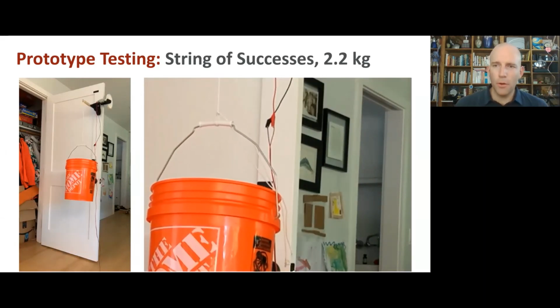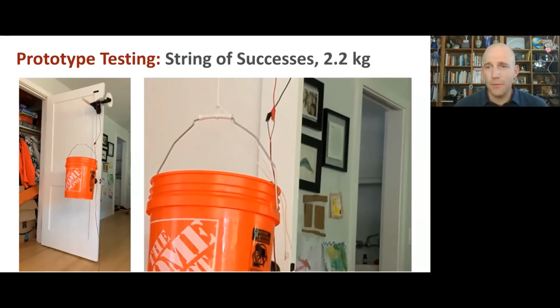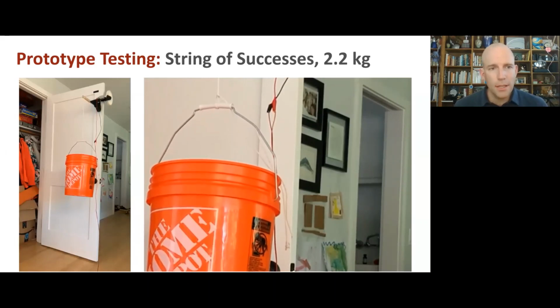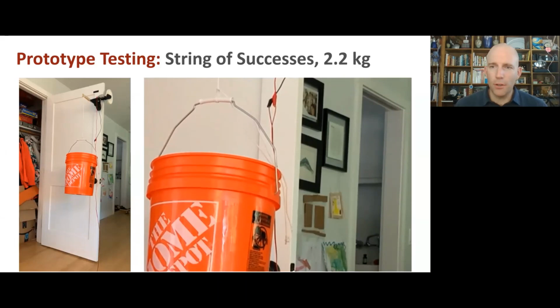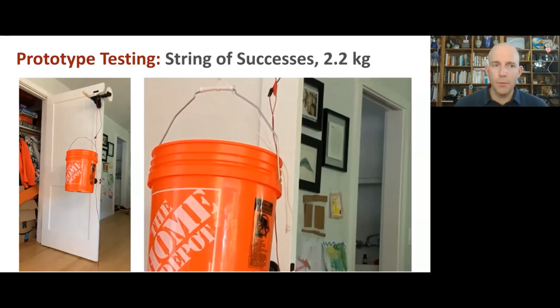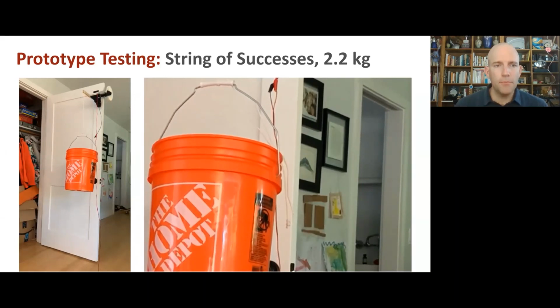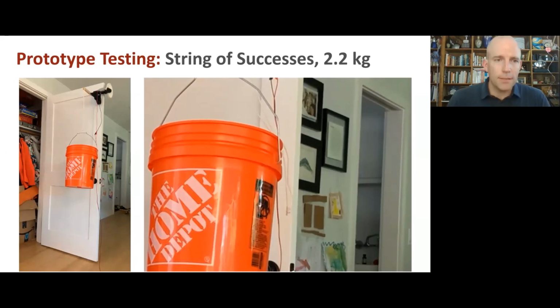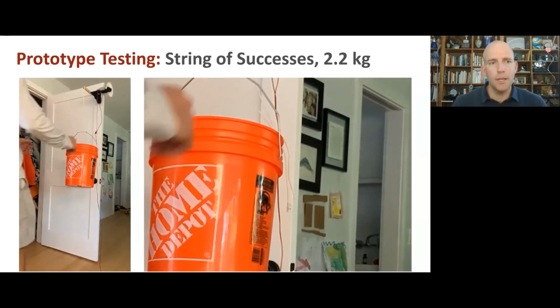And so I've jumped forward a little bit here because it's kind of a boring video. It just very slowly climbs up. It took about 2 minutes. We're not operating anywhere near the current limit for overheating the motor. And so, the motor could have lifted quite a bit more mass than this, about maybe 10 times the mass.